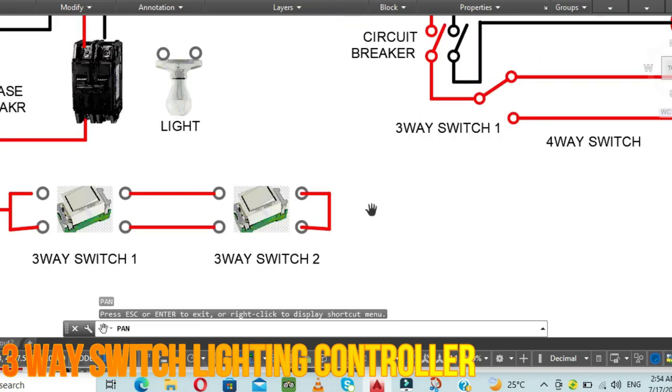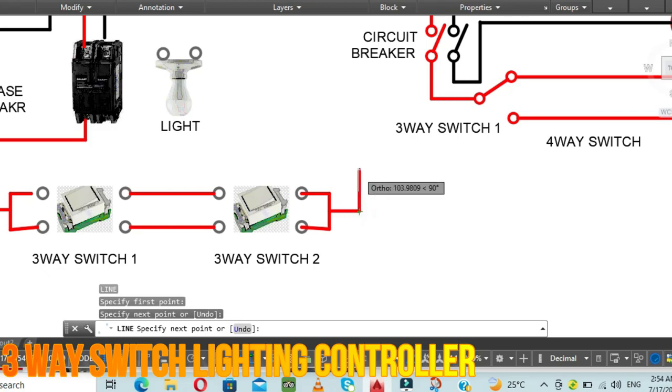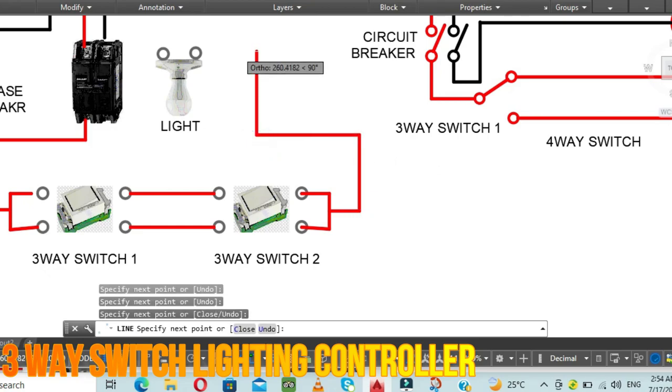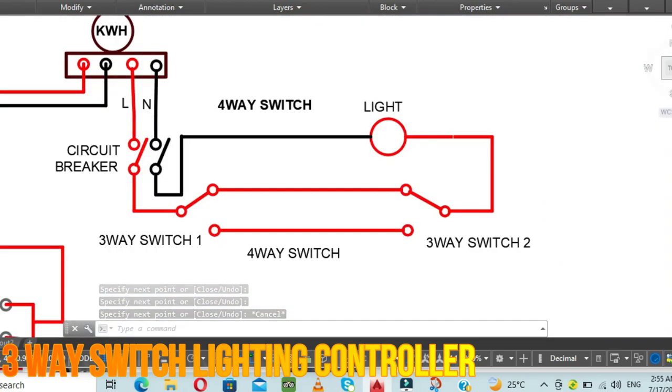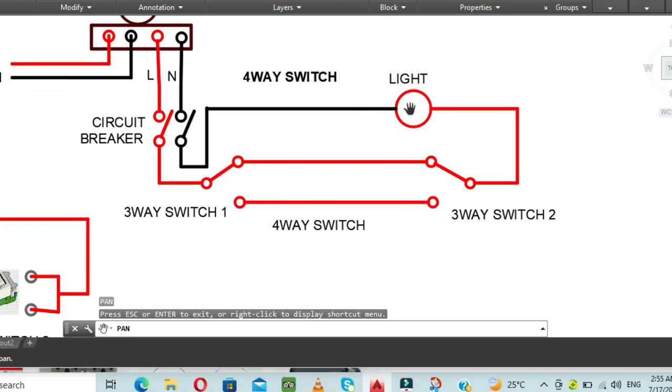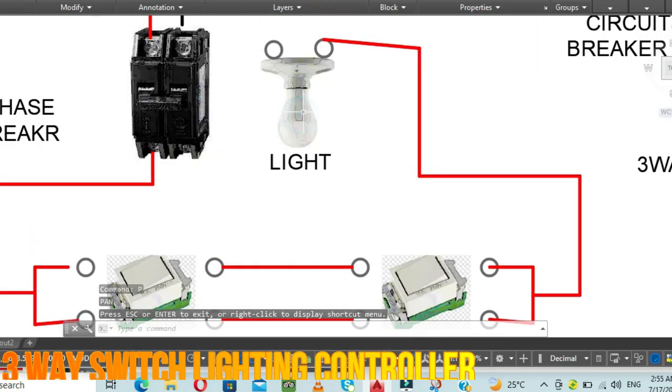So what we will do next is make a wiring from here going to the lighting. Okay, so this is the light now. It's already connected. As you can see here in the schematic diagram is the light. So from the light in and then the out, this is already line 2. It's going to the load side of the circuit breaker. So we are going to line 2.